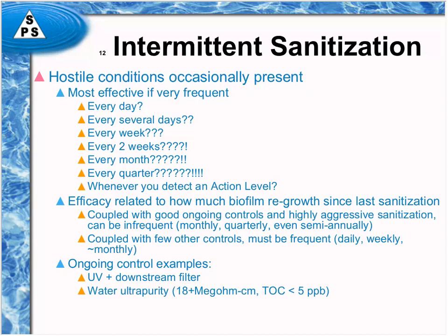Also having water that's very, very pure, 18 plus megohm and TOCs down into the single digits, less than 5 parts per billion. Those nutrient levels from that conductivity and TOC are such that you get very little biofilm growth as a result. The electronics industry has been doing this for years and years and years.